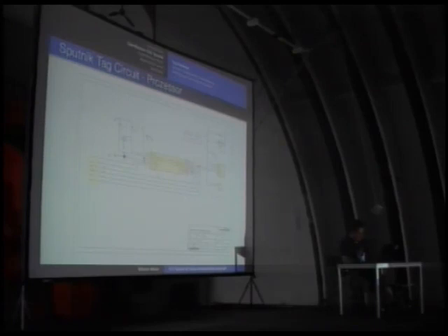This is the processor. I have a link for the data sheet. And then you know automatically, for example, if you want to know how to toggle the clock pin, you follow the line for the clock pin. You see, okay, it's pin 10 and it's RC0. And then you look into the processor manual how to use this. But the normal use for you is, as I said, very simple. You just have to follow lines and look what is connected where.